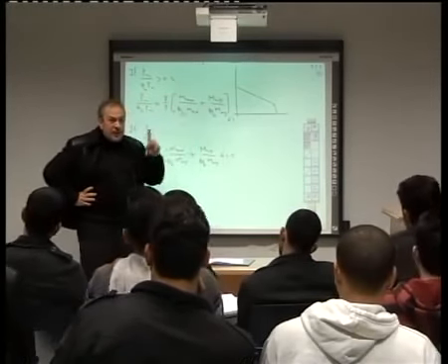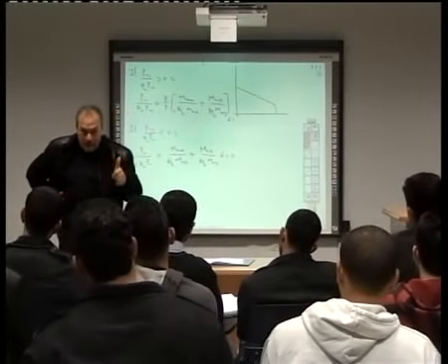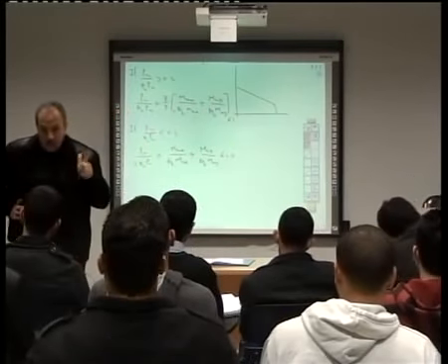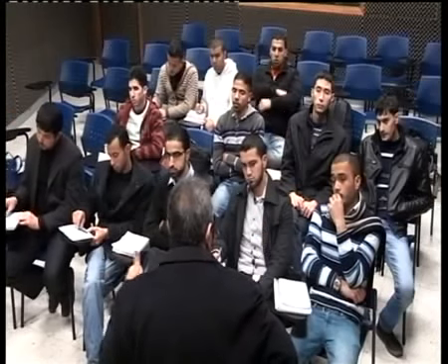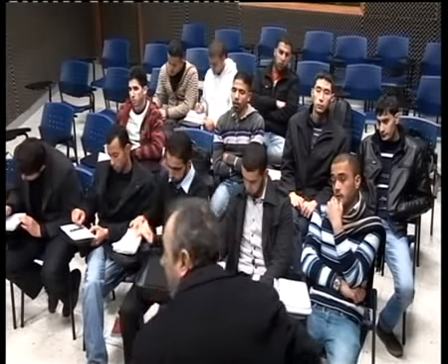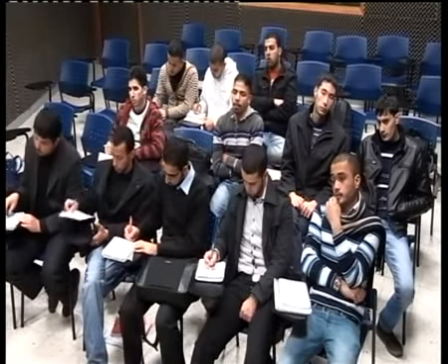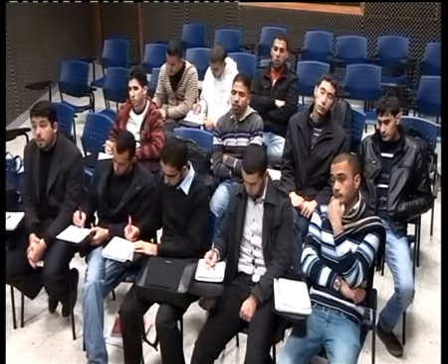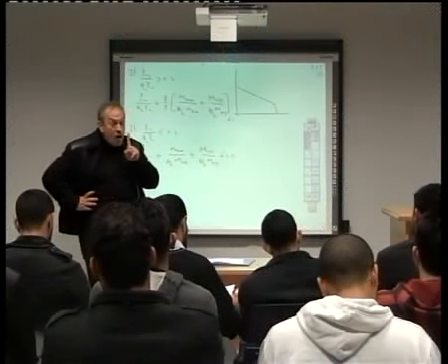MNX has to deal with local buckling and lateral torsional buckling. So you have to calculate it from local buckling, and MNY has to deal only with what? With local buckling. Only local buckling.